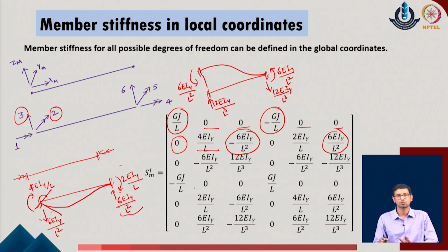So, I have just taken these values as we have done all these exercises multiple times in the given course. So, using these values now I can again reproduce the values. So, the first value is 0 because there is no horizontal twisting moment in the system. The second one, if you get the value of the moment, if you put with the right hand curl rule, the amount of the moment 6 EI y upon L square is located in this direction, which is opposite to the positive sign convention. So, that is why it has been provided with the minus of 6 EI y upon L square.